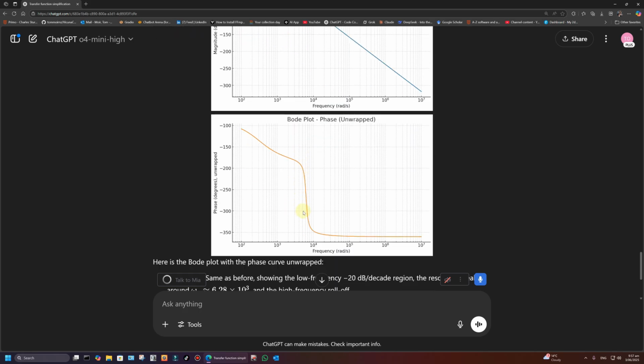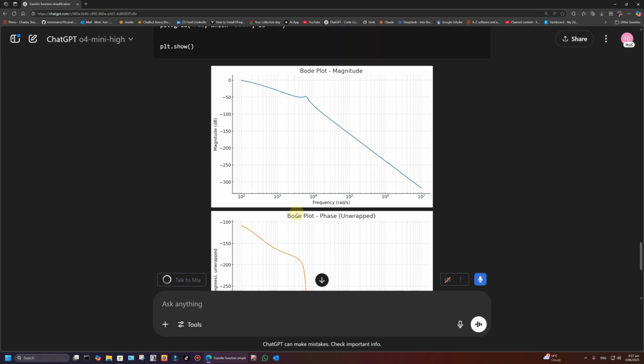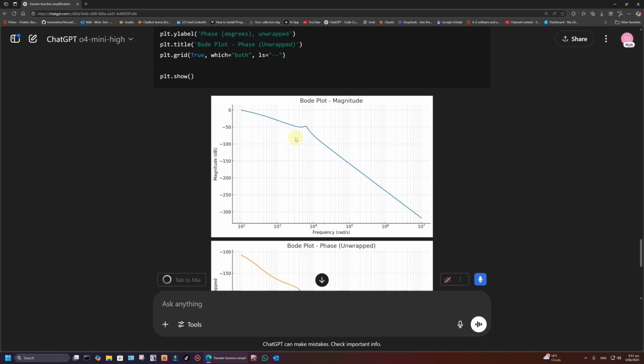So we're going to design, I'm not going to ask it to design the control system, put a controller in. I'm just going to play around myself to begin with. A naive way of controlling the system might be just to, let's say, increase the gain. You can see this, we can make this frequency the unity gain to begin with. Let's see, we don't want this resonance here to go above 0 dB, otherwise you get multiple phase margins and you get oscillations at high frequencies.